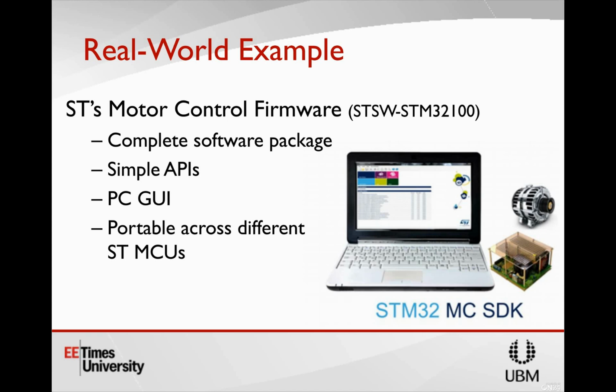So that's what I talked about: what we're really looking at is the voltage drop across that resistor. Since we know what that resistor is, we can make an op-amp circuit that will amplify that difference in voltage, such that we can directly translate it into a current when we read the output of that amplifier.